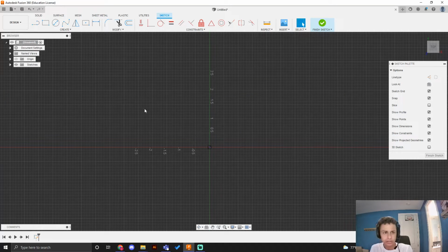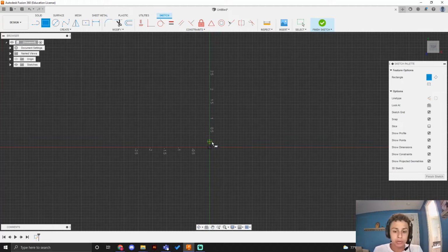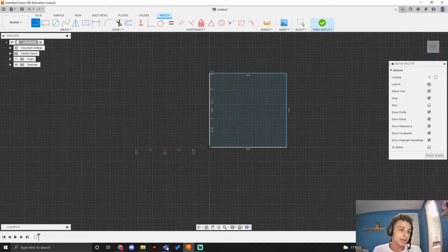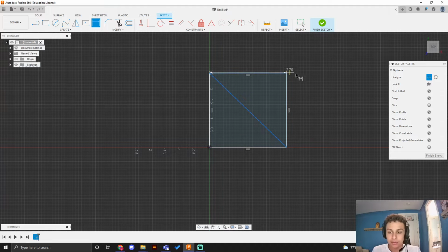But there's other ways to define an object also. Another really useful one is construction tools. So let's say I go to this line over here, and there's a construction tool right here. I can click that, or I can click X, and I'll select it. It's just personal preference what you want, but you can go from this corner to this corner, and then you can define that.